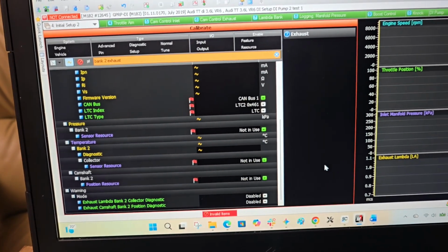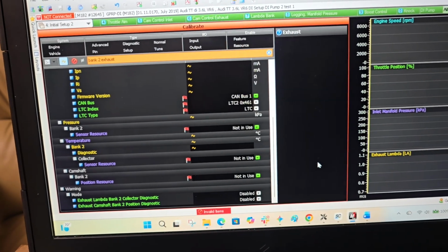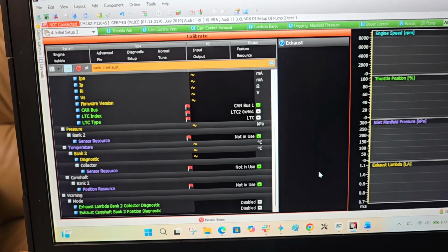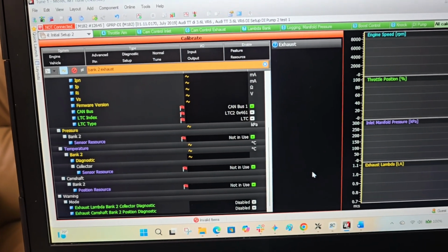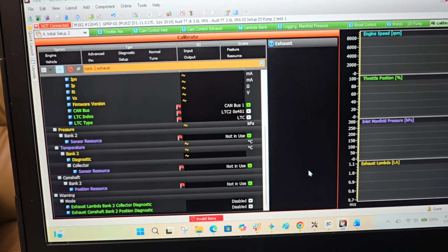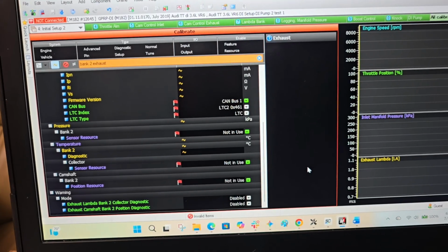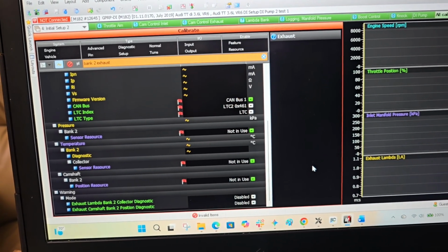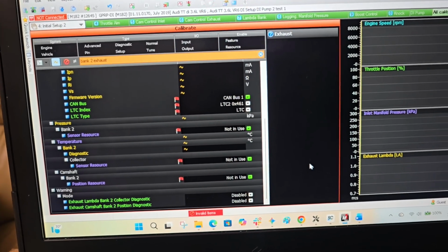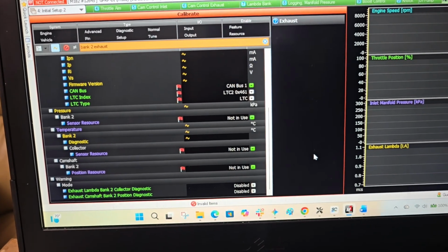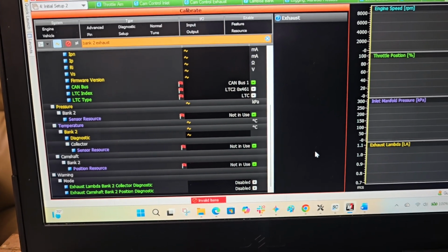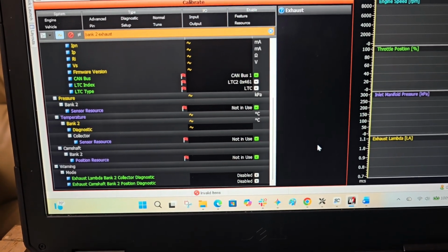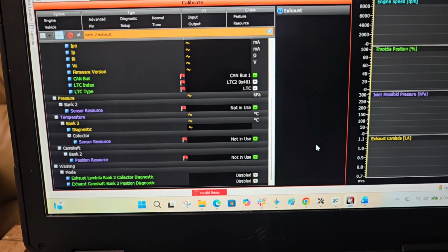Now we're slightly getting this engine configuration a lot more custom tailored to a VR6 direct injected package, which is a great thing. I've entered my camshaft profiles, which is very, very great. We actually monitored the camshaft through a complete combustion cycle. And what I did was measure out the direct injection pump lift per every stroke, as far as the base circle.